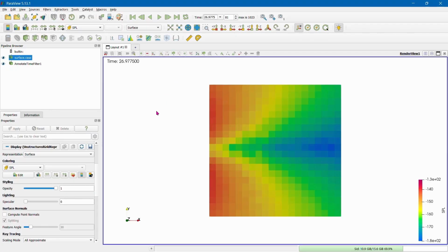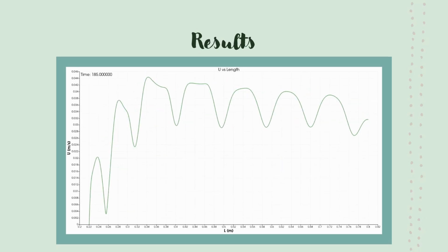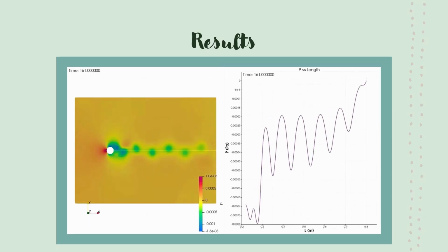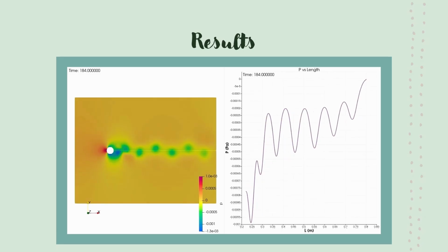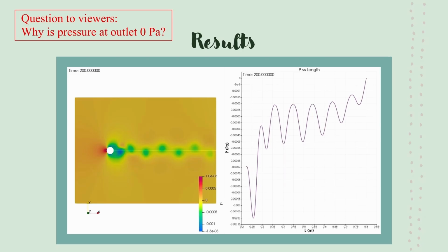And ultimately we can see the different data points that we were interested in, the power spectral density, the SPL, and subsequently how the vortex shedding effectively is occurring for our particular domain. So this is a plot of velocity with respect to the length away from the cylinder. Essentially what we see here is beyond the cylinder, let's say if we take a line such as this, what is the quantity of pressure, what is the quantity of velocity that's going to look like. We can see that the properties are oscillating, hence describing what our shedding frequencies are looking like.